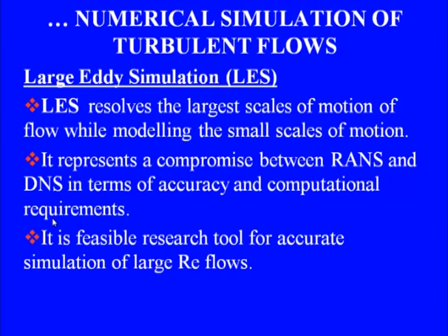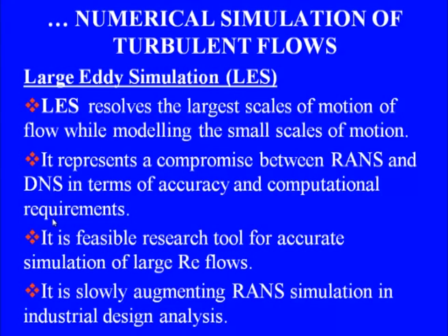It is a feasible research tool for accurate simulation of large Reynolds number flows at the moment, and that is why it is slowly augmenting Reynolds average numerical simulations in industrial design analysis by those companies which can afford a very large scale parallel cluster. They are now using large eddy simulation in the final design stages. For the initial design analysis, RANS is still what is being used. It is only in the final iterations that people go for large eddy simulation.